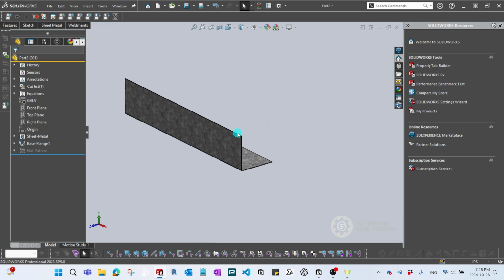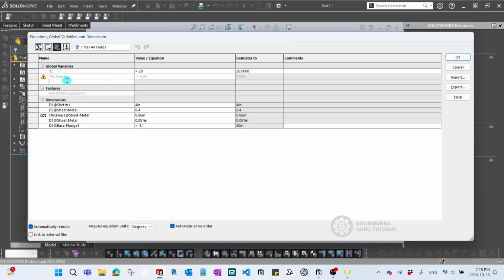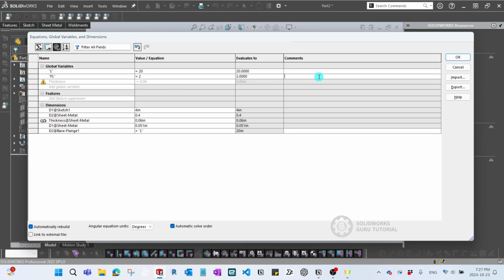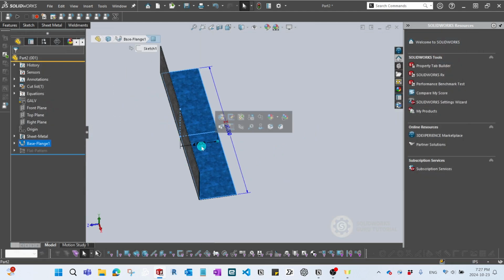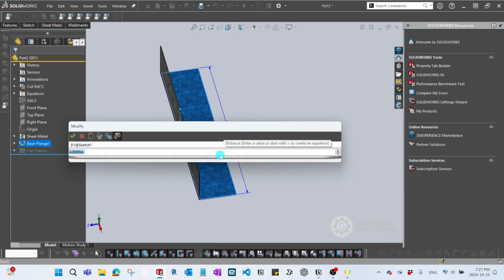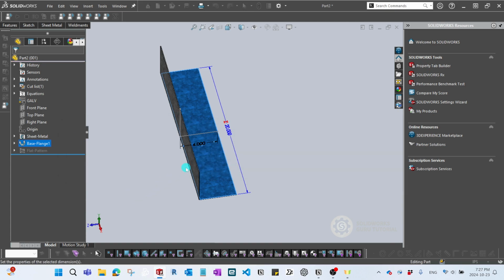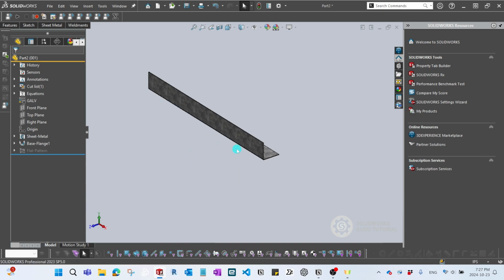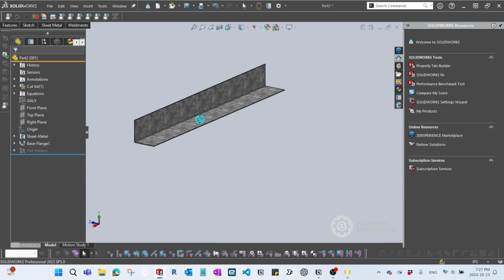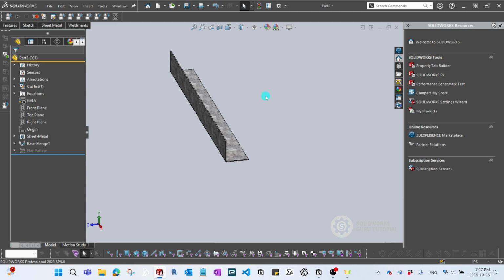Okay, and I think I can also assign FL, so FL for the 2-inch, which is gonna be the flange length. This is gonna be just a simple length, and I'm just gonna hit OK. Next, even for the bottom side, I'm gonna hit FL and hit enter several times to make sure all those equations are applied properly. Okay, this seems good, and all those values don't really matter actually.